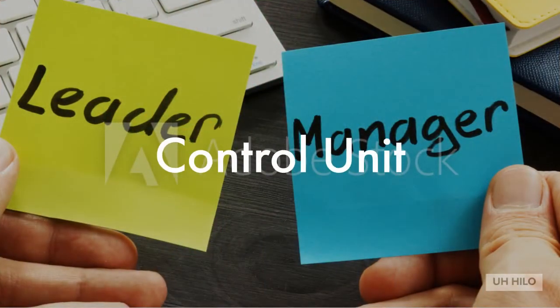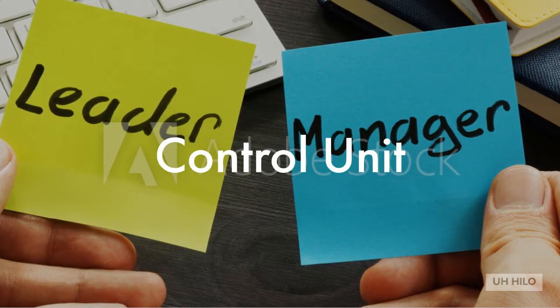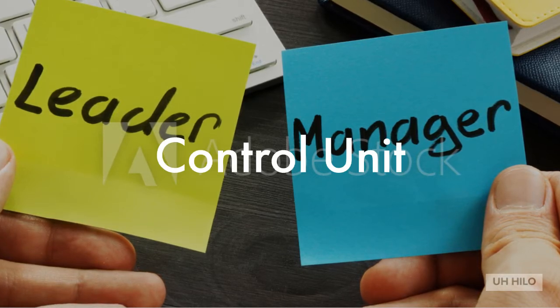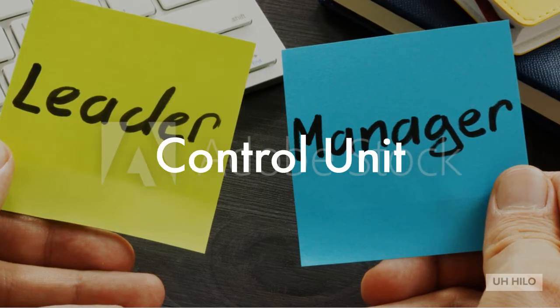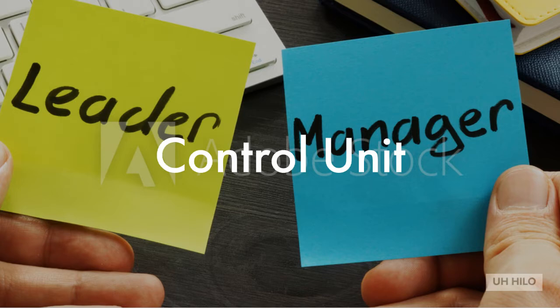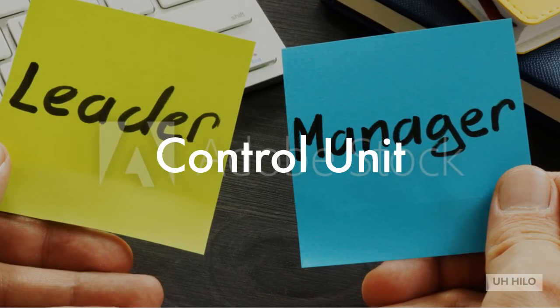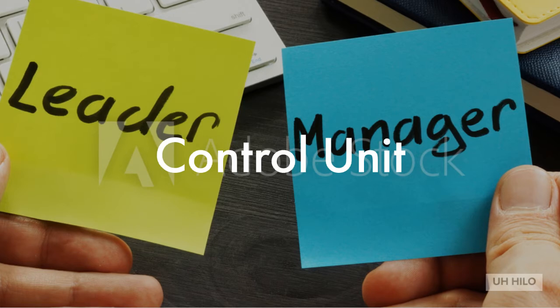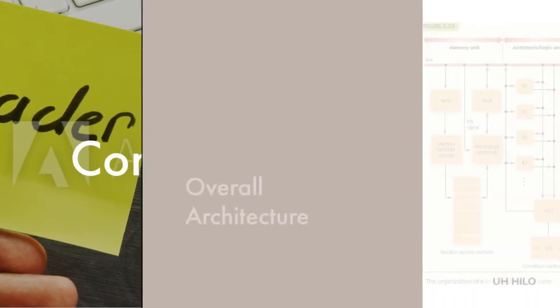If the ALU is the brains, then the control unit is the manager. It tells the other subsystems when to do their thing. The control unit contains a program counter, or PC register, that holds the address of the next instruction. There is also an instruction register, or IR, which holds the encoding of the current instruction. Finally, there's an instruction decoder unit, which decodes the opcode of the instruction and signals helper circuits, one per instruction.